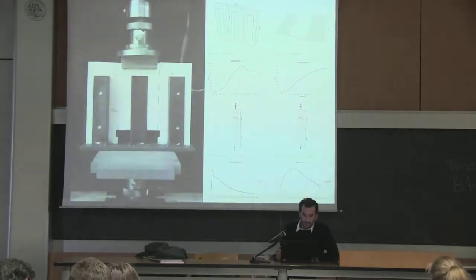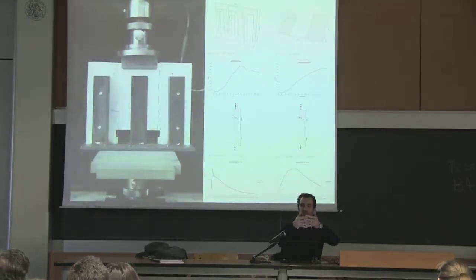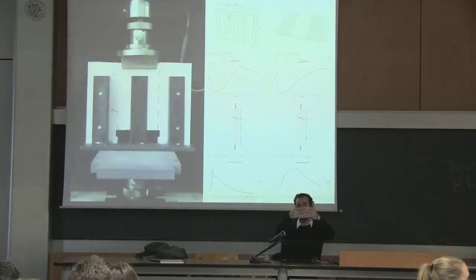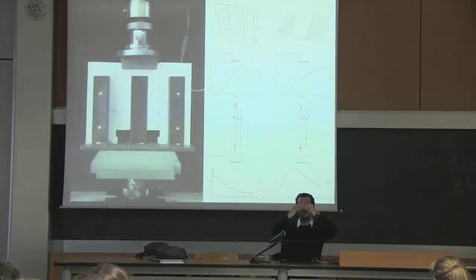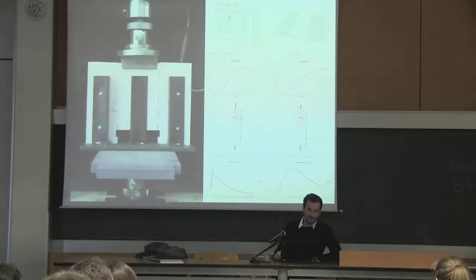So in order to productively use that, one has to really understand the behavior of these systems. And again, I think it's very straightforward, and you don't need to be a structural engineer to do so, by knowing that these finger joints are very good in withstanding forces in the plane of the plates, the shear forces along the plane of the plates. So if the plates want to do this, they're locked in place. Very bad in transferring bending moments because they're like pivot joints and cannot withstand any tension forces. So again, engineers would consider that as a big challenge when it comes to designing a construction scale plate structure.